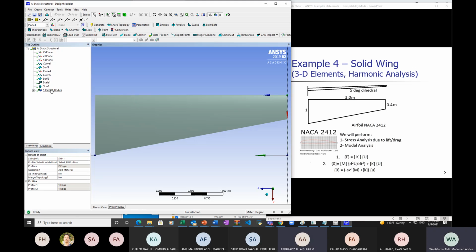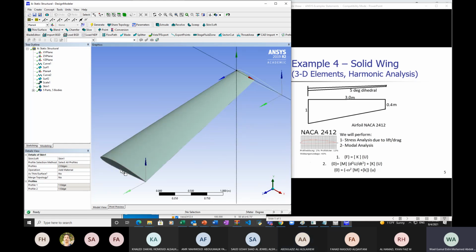Doctor. Yes. Can you repeat the last step because I had some issue with my. Do you have the two airfoils? Let me show it in here in 3D. Did you have the two airfoils? Yes, I have them. Okay, so you go click on skin loft. So all he needs to know what are your two airfoils to loft between. So you will pick the small surface while pressing on control, and then you will pick the other one. So I need to pick two of them, the small one here and the big one here, and you click apply.